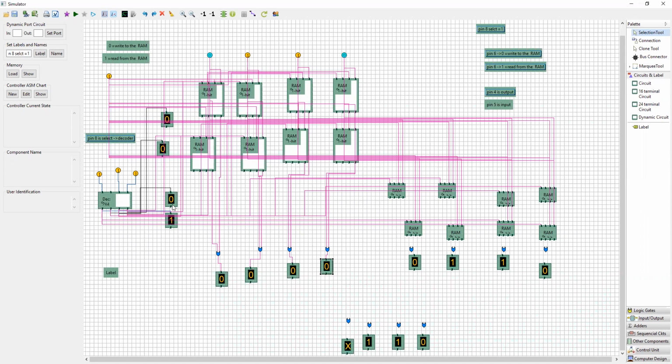First, the operation is very important right now to understand the flow. Please concentrate carefully. First, I want to insert data into the first row of RAM. I want to insert 1010 into the first row. To insert into the first row, I need to select the first row. How can I select it? With the help of the decoder. I have set this to 00, which means it will select the first row.